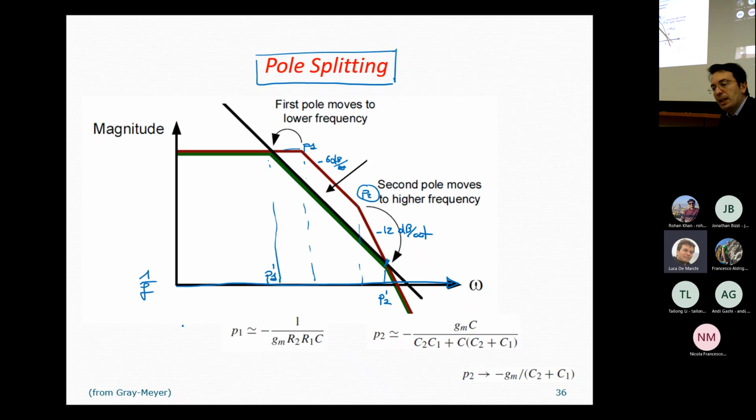So overdrive of transistor number 5 plus overdrive of transistor number 1 plus threshold. Please remember that in this calculation, each VGS should be equal to this quantity, while the VDS should be equal or larger than the overdrive. Okay?